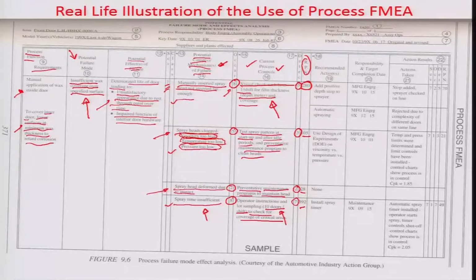in terms of maybe either decreasing the occurrence percentage of a certain defect cause, or again do some design improvement so that the failure mode may not be as severe. So in this case it is ruled out because the process is fairly well established, the design is well established, so we can't do anything about the severity. But obviously we can make some countermeasures so that overall occurrence of a certain defect can reduce, and also the detectability can either be at the same level or go slightly up, so that overall the RPN, because of the dominance of the reduction of occurrence, may come down.